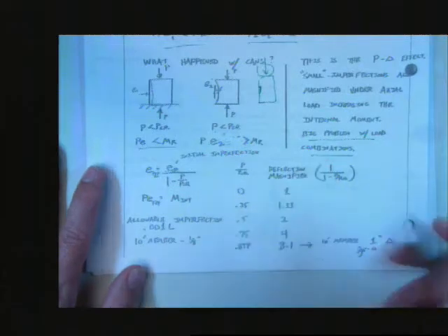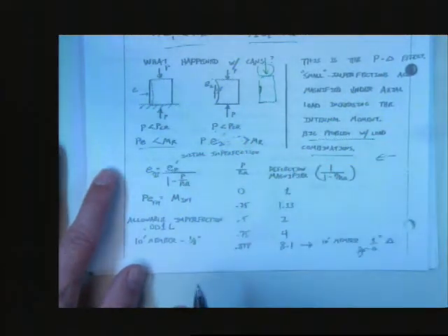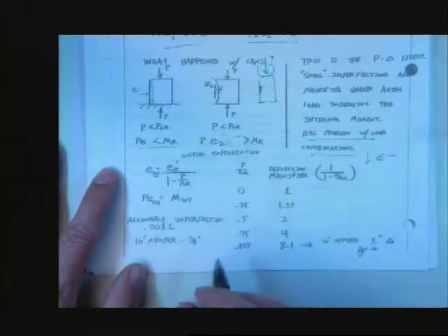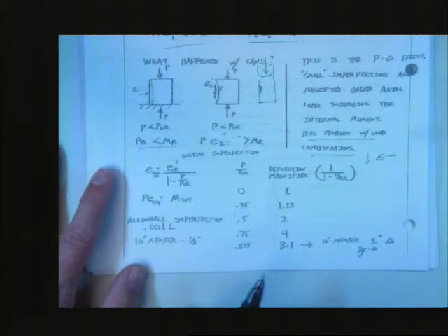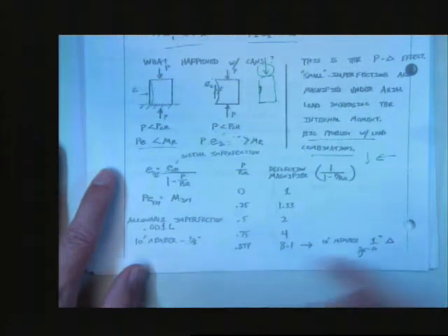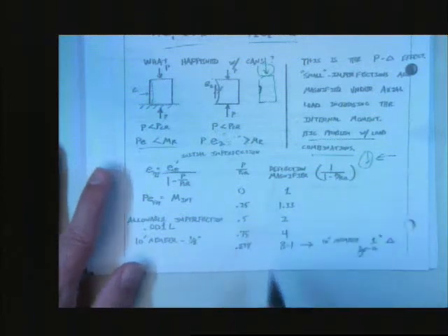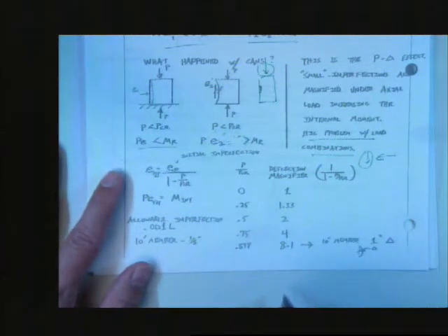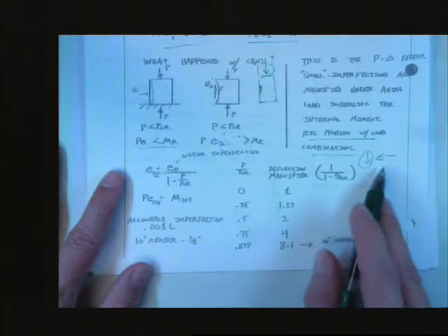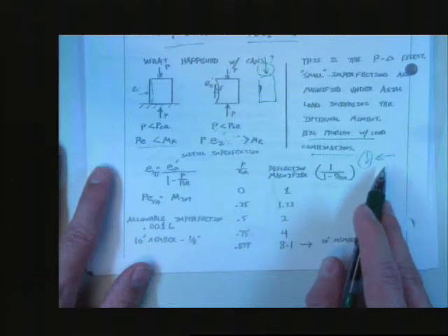So because of that, when our horizontal loads are high, our axial loads are usually not as high. Usually in buildings. Okay? If you have a structure that's almost entirely led by dead weight, like a bridge, then your axial loads are going to be high when horizontal loads come in. The good thing about our columns is they're usually pretty skinny. They don't really pick up a lot of wind load. They're just too thin. The wind goes around them. What they do pick up is 18-wheeler impacts. Okay? If they can hit them, those truck drivers will hit them. And when they do, that can cause issues.